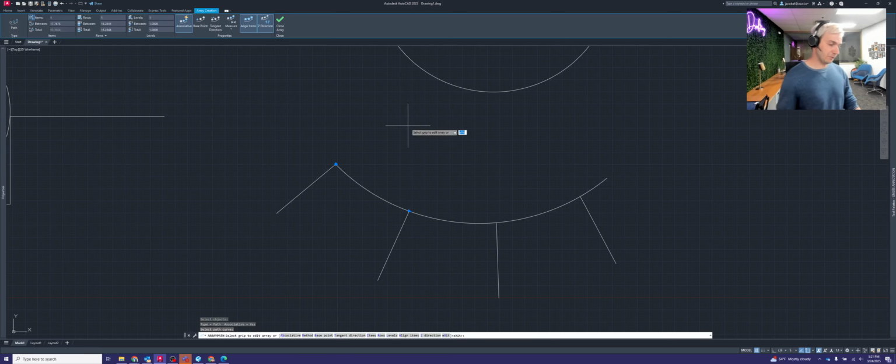Okay, so before we can close out of that, there are some things I want to look at with you, and we'll definitely be getting in more depth with this command as we go on. But the array path command allows you to select the distance in between each line that you're copying. Right now, it just randomly came in at like 17.76. We're just going to make that 5 inches apart.